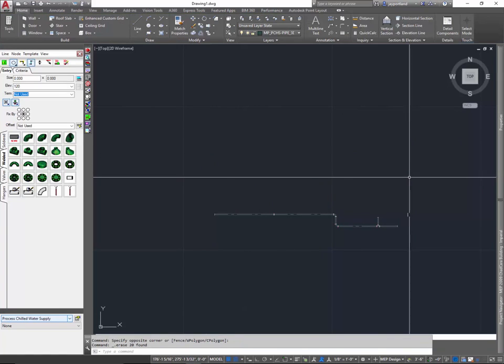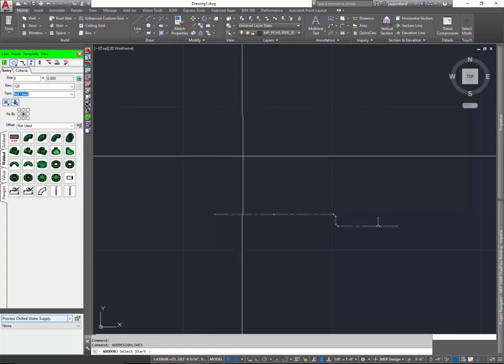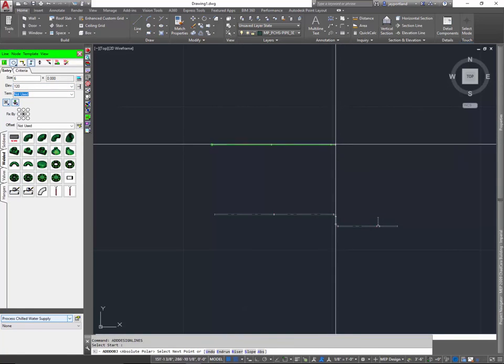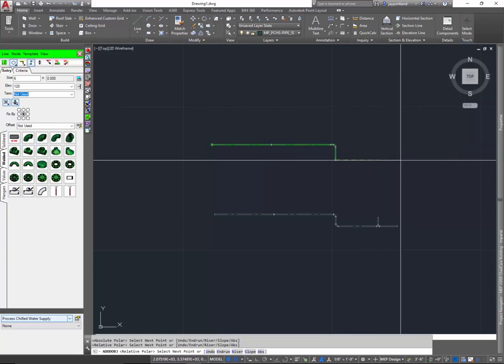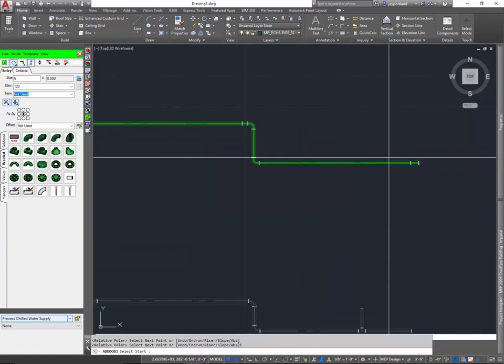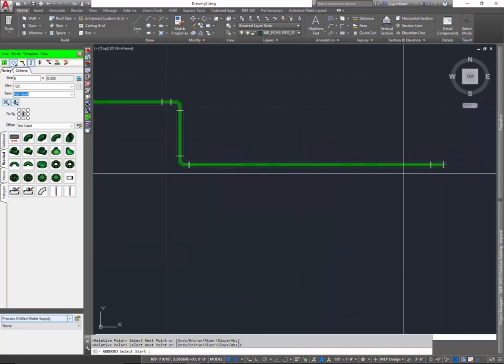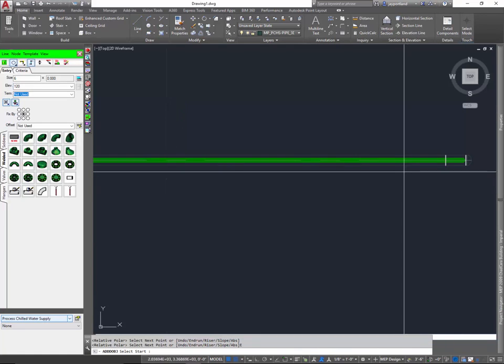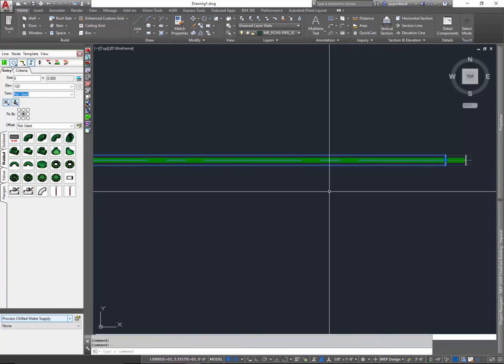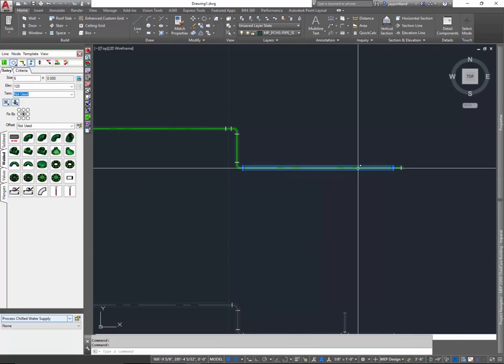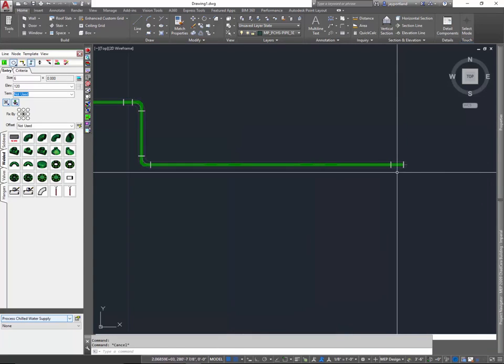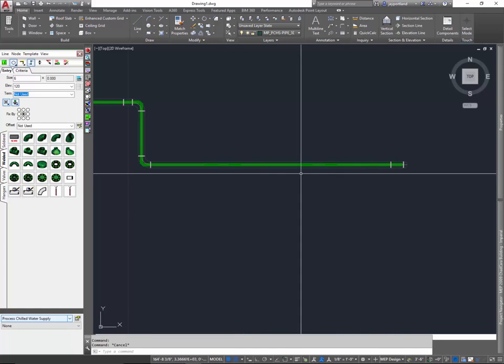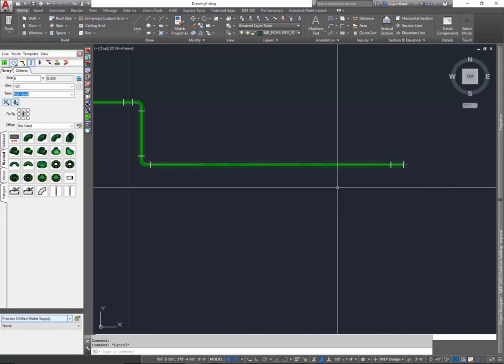Now, a few additional details. We are going to add in some 6-inch piping and 120 inches. Let's go ahead and add some piping now. So that was the design line, and what the design line does is it facilitates adding these components. Now, you'll notice that I have a big, heavy center line here that represents my design line, okay? But then I also have the piping that's associated right around it here, and according to my minimum cut lengths of 20 feet, which is 240 inches, that's where the shop weld will be placed, okay?